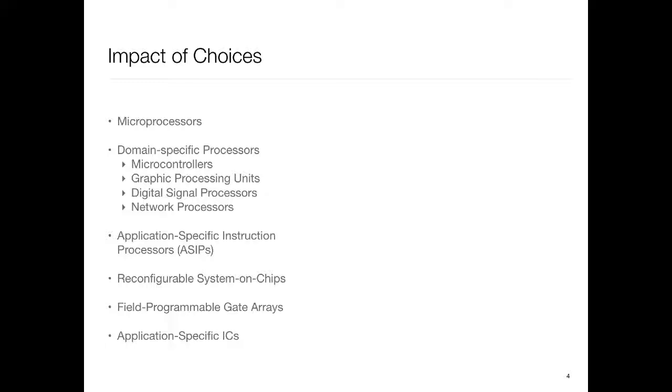If your FPGA is sufficiently large, you can run a processor on the FPGA and then run the operating system on top of that processor. So multiple levels of indirection going on. And then finally, at the customization end, are ASICs. Now you say, I know what I want and I'm going to put everything down in silicon, and there are various ways to speed up the fabrication of ASICs also.